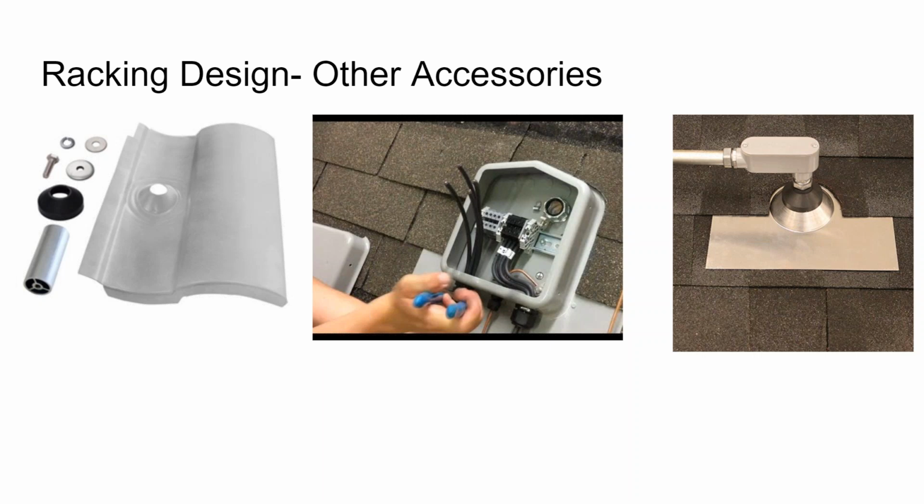And then the other thing we didn't get into is load side connections can accommodate 120% of the service panel's amperage rating. So there's a special rule we'll get into tomorrow that if you have a 200 amp service, you can add 40 amps of solar to give you 120% total.